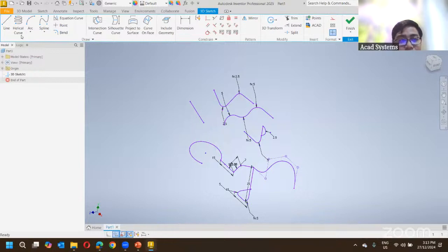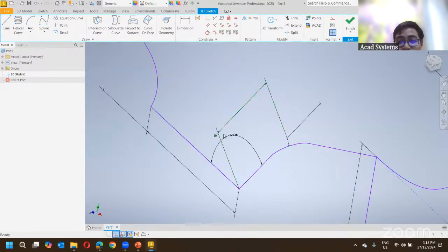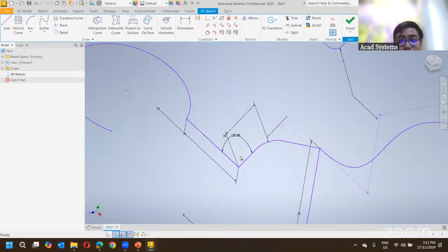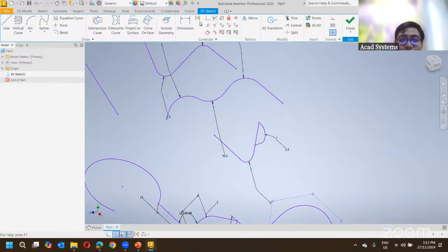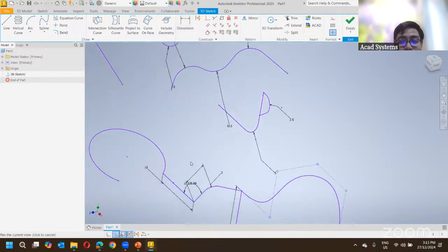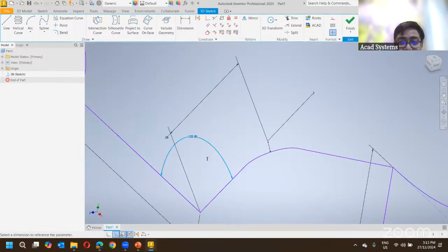With this, since we have added the lines and we can input the value for the length and also the diameter, that will be constraints. The constraints can also be applied later on by using these constraint tools here. Currently, if I want to edit, I can just double click and edit the value, maybe make it somewhere around 100 only.